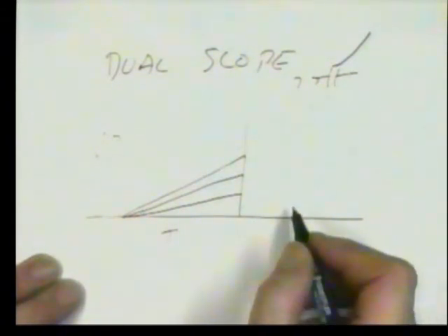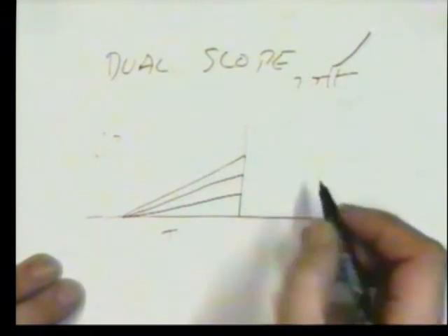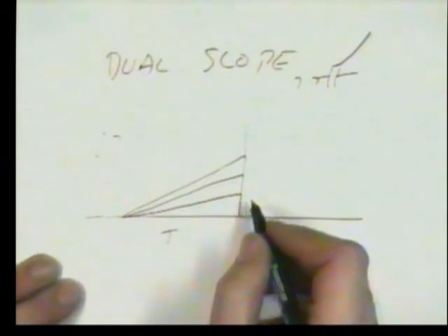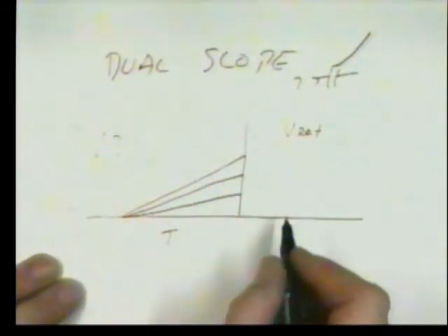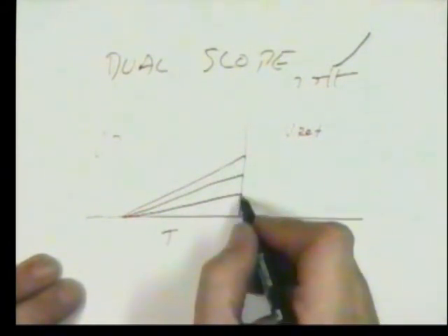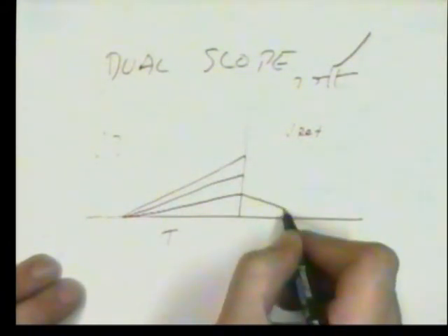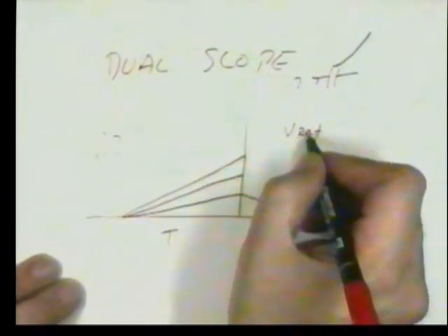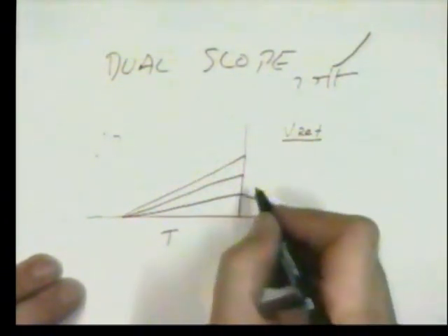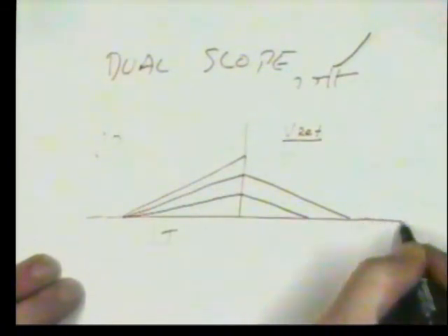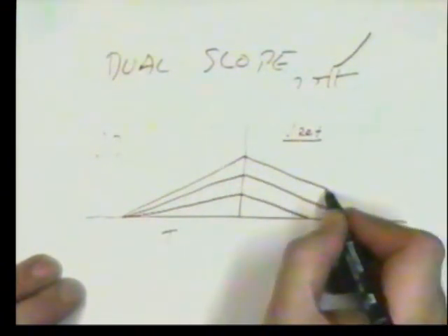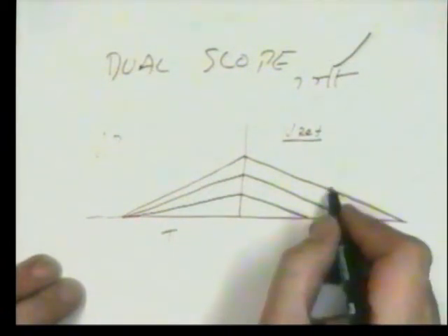Now we switch onto the capacitor a known reference voltage, and the thing will start discharging. But if the reference is a constant, they will always discharge at the same rate. So the discharge patterns are always parallel lines.